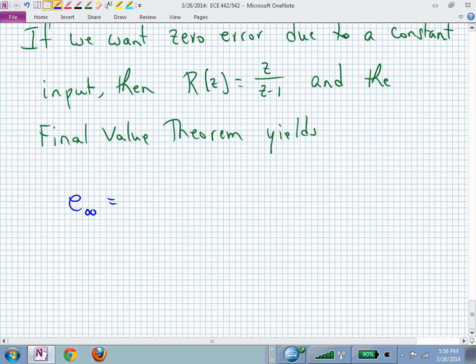And what is that? Well, in an analog control setting or in continuous time, you're saying e to the minus 5 is 1%. It's actually 0.006, so it's less than that. But we're getting close to 0, e to the minus 5 time constants. So if you know your dominant time constant, 5 of those, and you're at infinity.